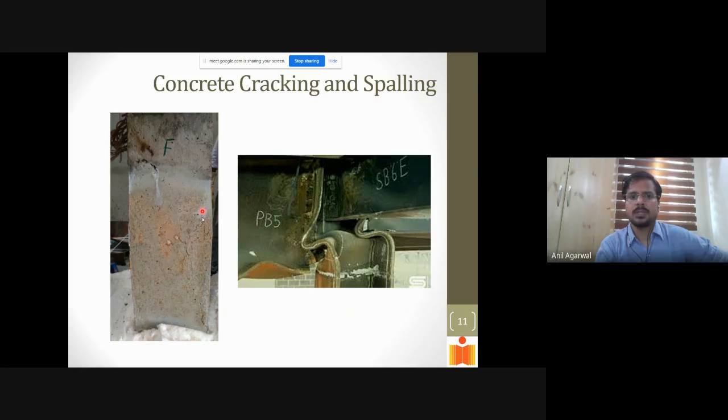Typically, what happens to concrete? You can see it undergoes a lot of cracking, like what you can see here. Can you see the cracks in the concrete member? This is a concrete column, a square column, that we had heated in our lab. And you can see the discoloration of concrete, right? Concrete generally was originally of this dark gray color because it was a relatively new specimen. The part that was heated to almost 1000 degrees centigrade changes to almost this pink orangish color, right? And that is basically the granite aggregate, which is gray in color, that itself also changes to more of a pink orangish color.